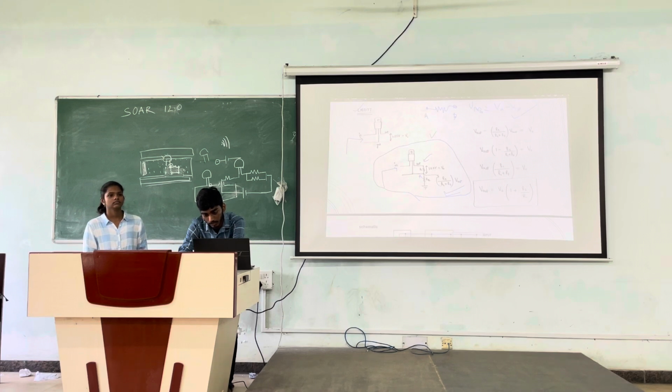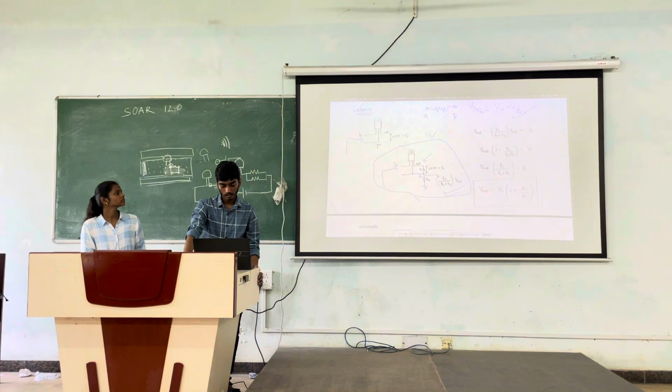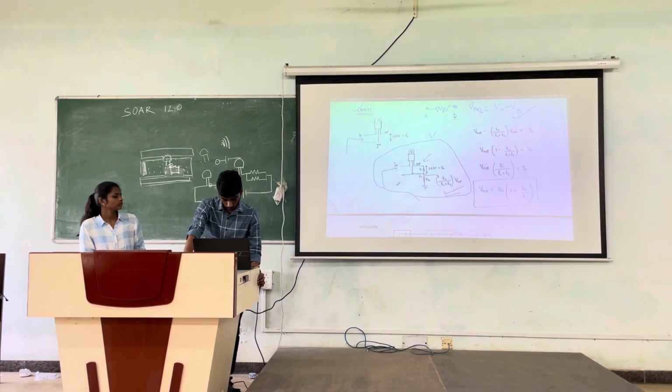This is just a basic thing: we subtract the potentials of these 2 points and get the potential difference. So we are trying to get the potential difference across this R1 resistor, so we do V out minus VA, where VA is R2 by R1 plus R2 times V out, so we put it directly here. So V out minus VA should be equal to this V naught.